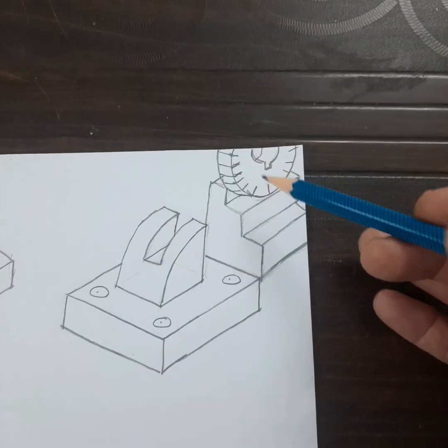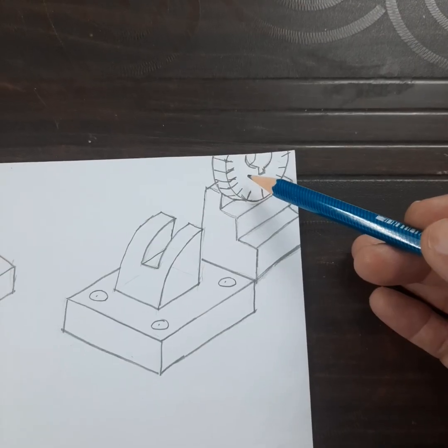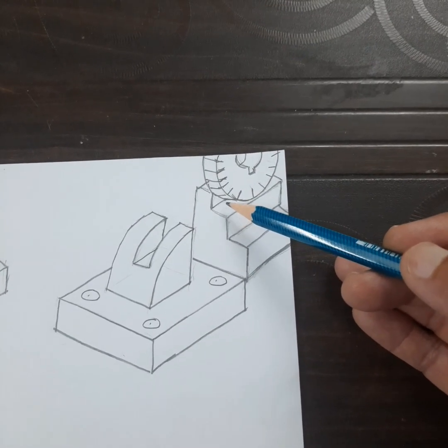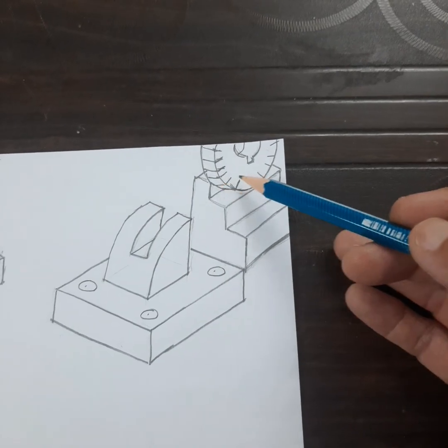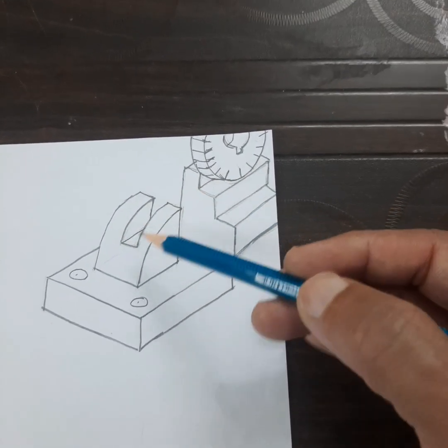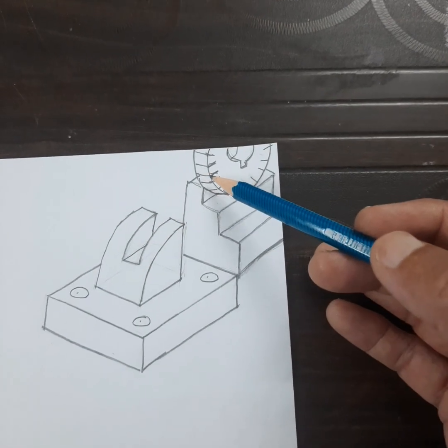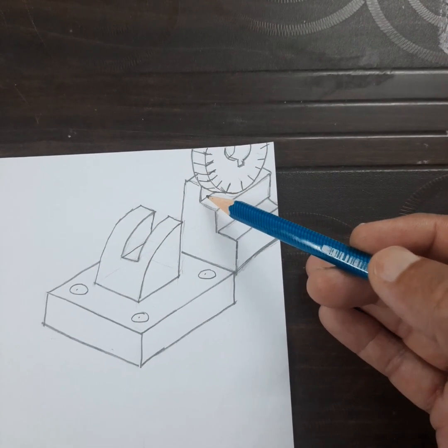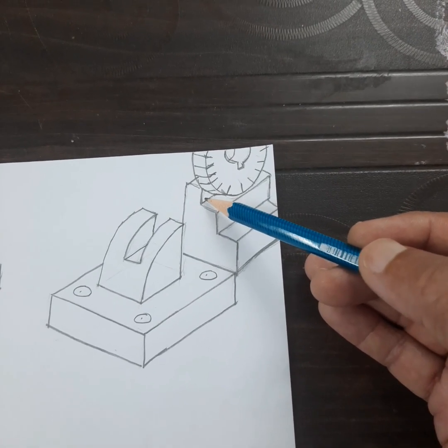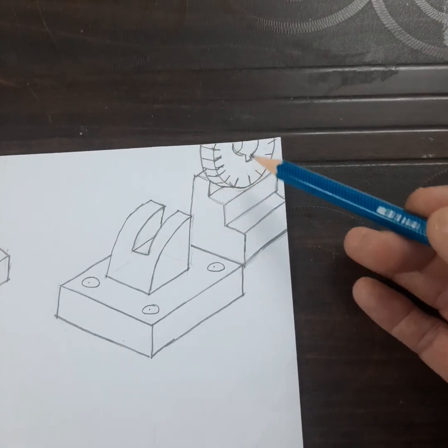A support. So the rotating cutter is made to touch the base of the setting block, in such a way that on passing the milling cutter over the component, the required depth of the slot will be machined. Similarly, the side surface of the milling cutter is set to touch on the side surface of the setting block for the purpose of positioning the cutter.